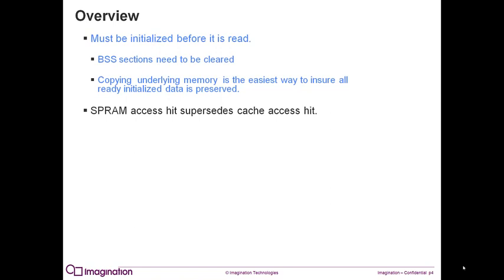It is also possible, if you are using a TLB, to have a virtual address mapped to a cached area and another virtual address mapped through the Scratchpad, but both using the same physical memory, in which case you could have updated values in either the cache or the Scratchpad, and one not seen by the other, so you would need to avoid this situation.